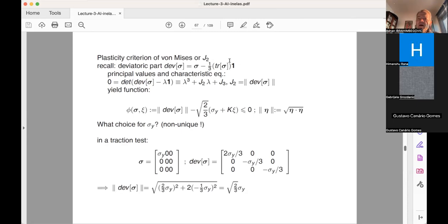So this will be the ratio between the hydrostatic pressure and change of volume. And you take a shear modulus, which will be a ratio between the deviatoric stress and the change of shape. So this is the kind of thing for metals that we're going to be using. Basically, you need, let's say, the shear modulus to characterize behavior, and you need the deviatoric stress.